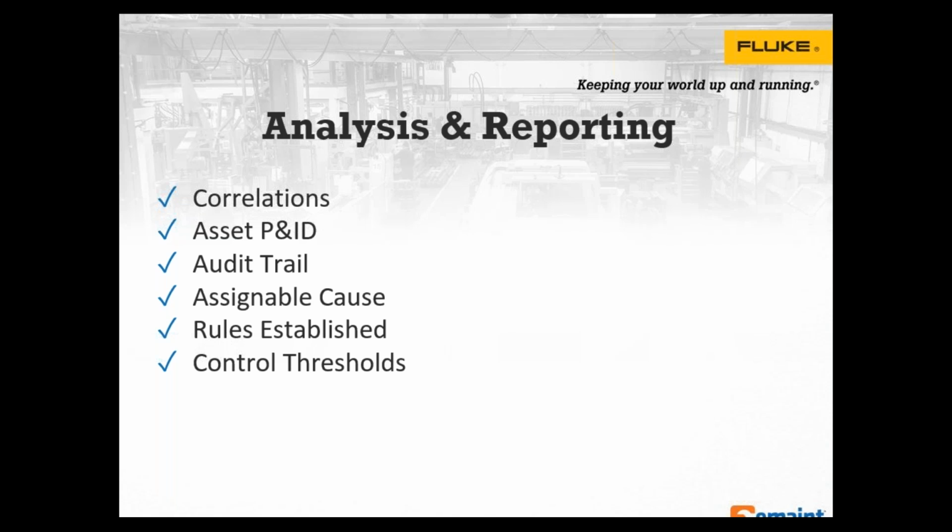On the plate of the motor, it says maximum current. If you exceed the maximum current, you want to be alarmed. You can set the threshold to that. In some cases, sometimes it's too late. So you want to make sure that you catch it in real time.